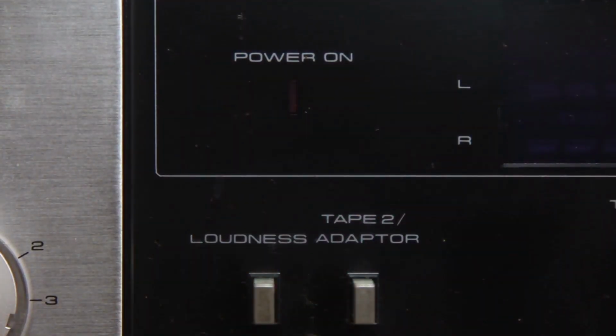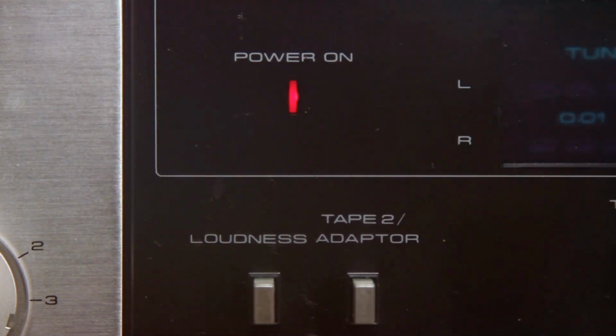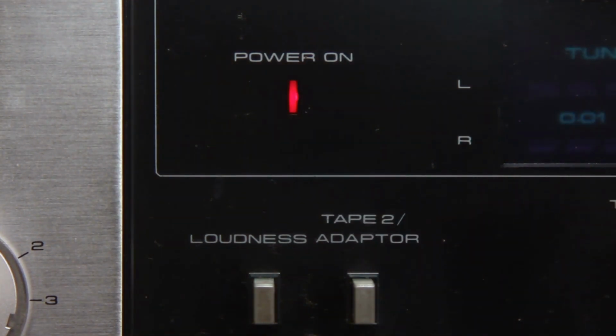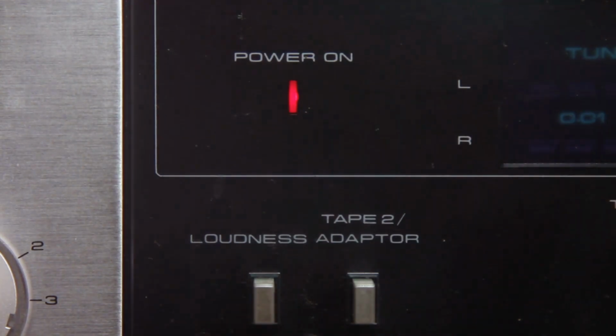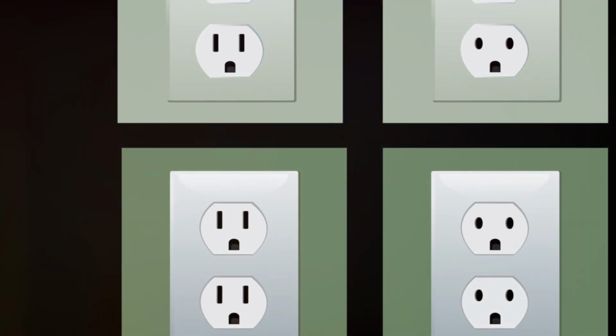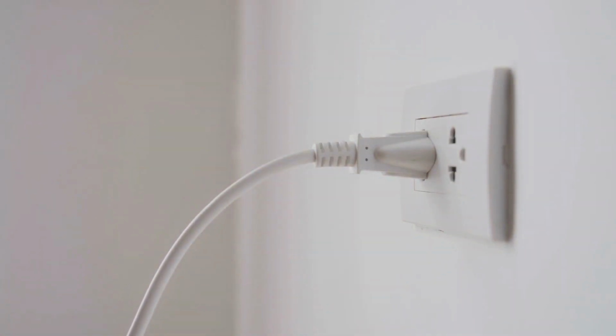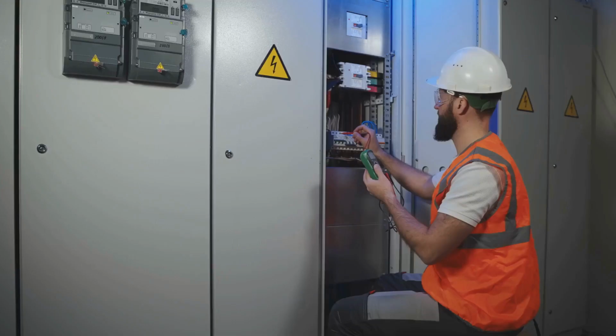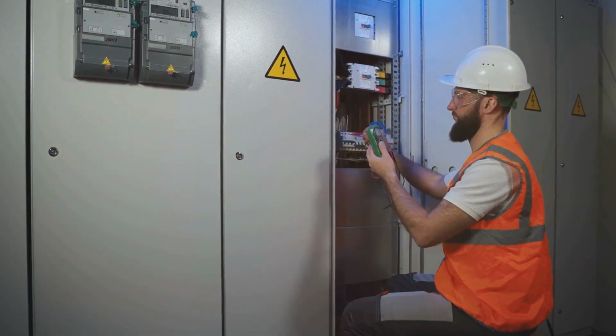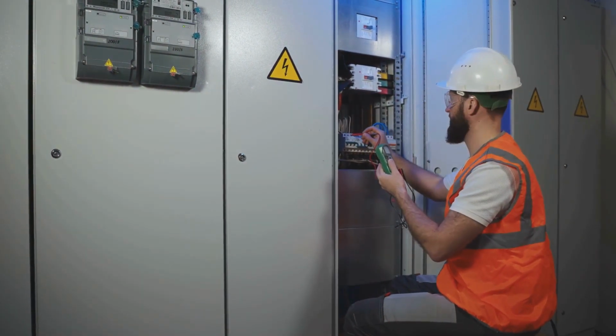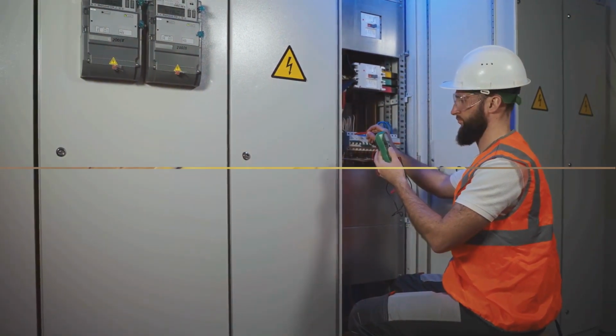So, how do we find out this maximum capacity? It's often indicated on the circuit breaker or in the electrical panel, usually in watts or amps. And how about the total power of connected appliances? Just add up the wattage of all devices plugged into outlets or wired directly. Remember, the sum of the power from all connected appliances should never exceed the circuit's maximum capacity.